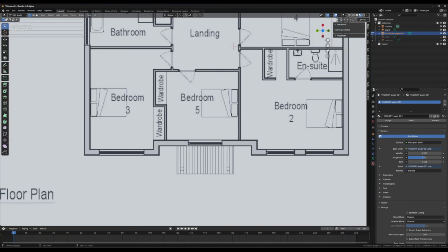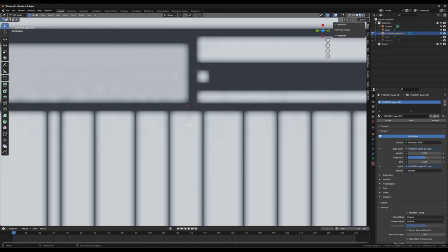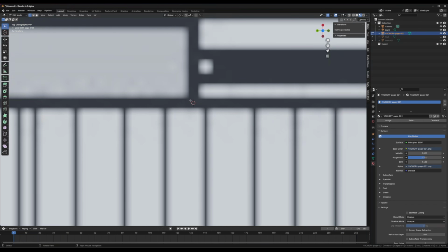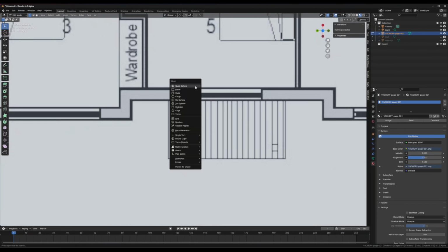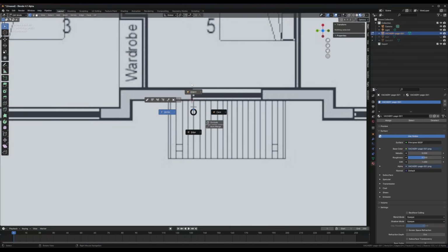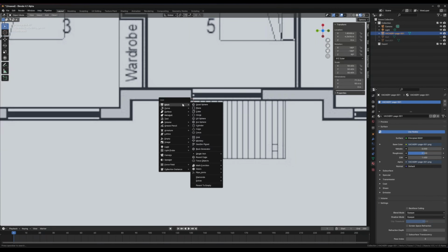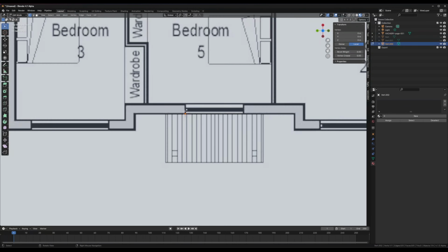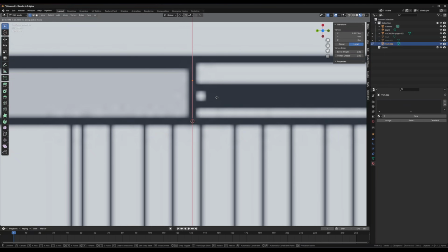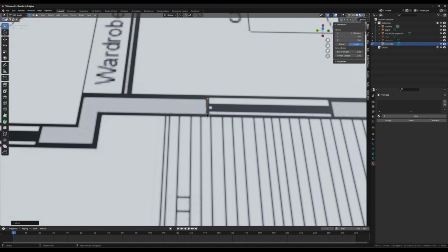We can press Shift plus right mouse button to add the cursor here to the corner, and we'll just add it right here in the center. And then press Shift A, and make sure we're in object mode. Shift A, Mesh, Single Vert. If you don't have the single vert, look at the other video about the single vert. Once we have the single vert, we can extrude it up, and if you click it, up in the top left you'll see the distance of how much it's been extruded. But we're just going to go with that.